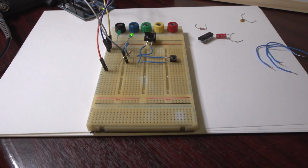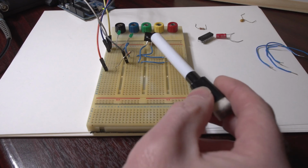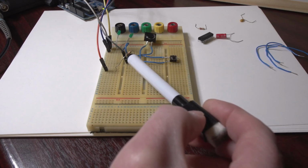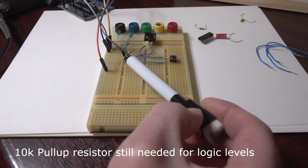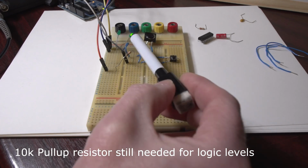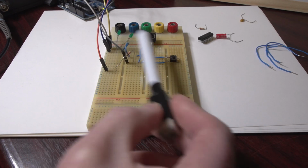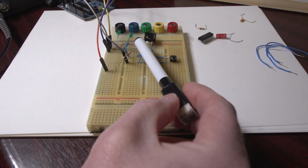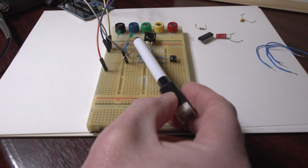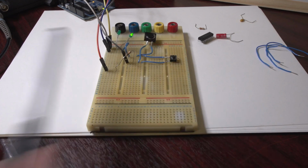Straight away we've saved a little bit of money. If we were in a production environment, I'm sure the accountants would be very happy with that. Let's have a look at this. So what we still do have is the 10k pull-up resistor. We need that to get the logic level to go high when the button's not being pressed. Other than that, we've still got our 2 LEDs. We've got the interrupt LED, status mode if you like, fast and slow, and we've got our flash LED, which is indeed flashing at the moment at 1 second intervals. So we know we're in a slow mode. That LED's off. That's telling us we're in a slow mode.